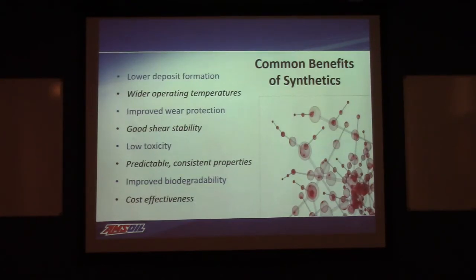Common benefits of synthetics: because of their purity, they tend to form less deposits, which can be an issue in a variety of different applications. Compressors come to mind on it. They have functionality over a broader temperature range, great for Arctic conditions, yet they're perfectly functional in the Sahara. Improved wear protection. Because of their ability to maintain their viscosity, to maintain their load carrying ability, they can provide a higher level of wear protection on there.